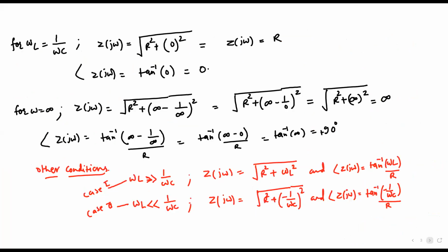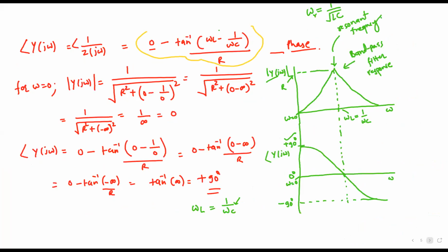What about the admittance? So this is the plot of admittance. We see that at omega equal to 0, admittance is 0, and at the resonant frequency, it takes the value of R. R is 1 ohm in the simulation. So it's 0 dB or 1, and then it goes to 0. The phase transition is from +90 to -90. It passes through 0. So let's verify that.